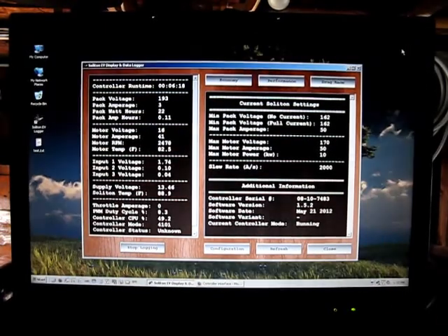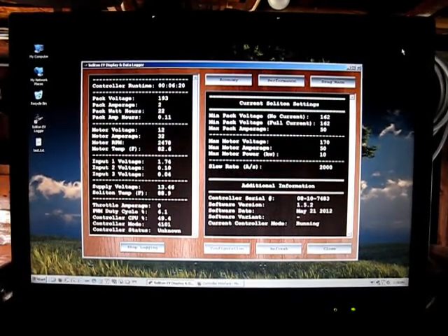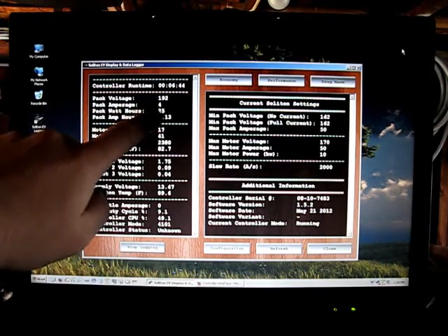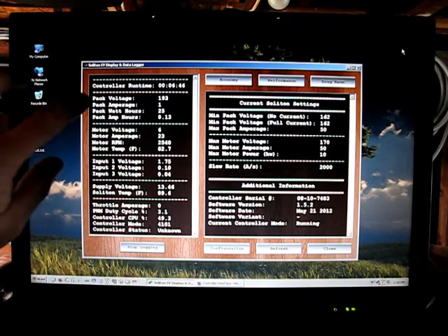So we're going to let it chug and whir and sputter here, now at the 2,500 RPM range, the fastest that we can idle the motor at with the Soliton. And we'll let it go, and I'm going to go to work, and when I come back I'll find out how it turned out, or if my car is a smoldering pile of ruin on the floor. Also, I do notice that with the increased amp draw, we're now pulling 2 to 6 amps out of the pack, and the pack voltage is sagging a little bit more.